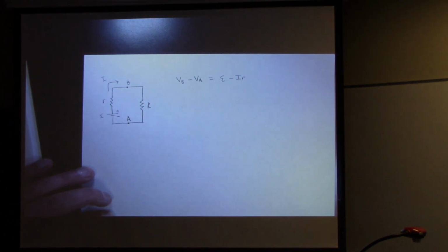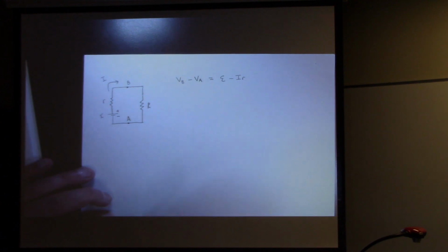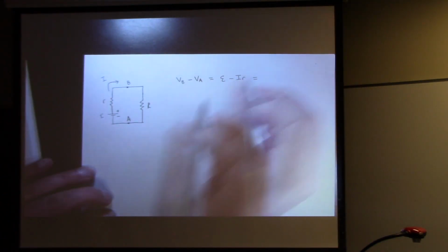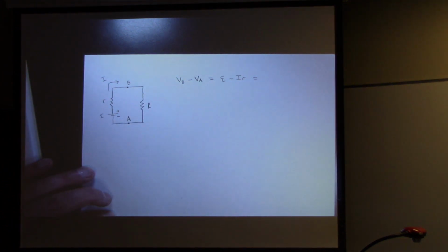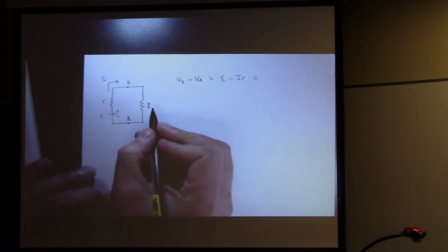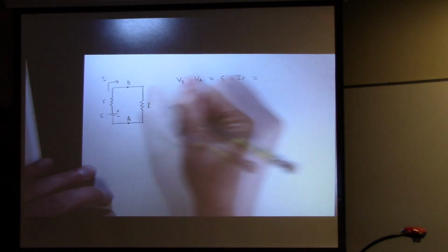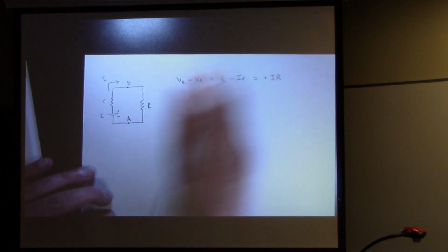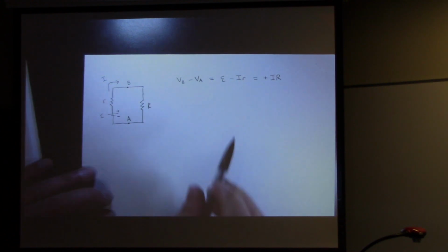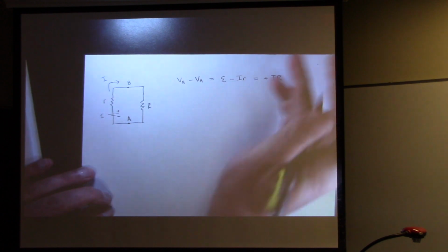That's just Ohm's law, and since we're going with the current, we have a negative voltage, or a voltage drop. We can also go this way, across the load resistance, and if we go this way, we're going against the current. Whenever we're going against the current, we have a positive voltage, or a voltage increase, this time given by plus I times big R.